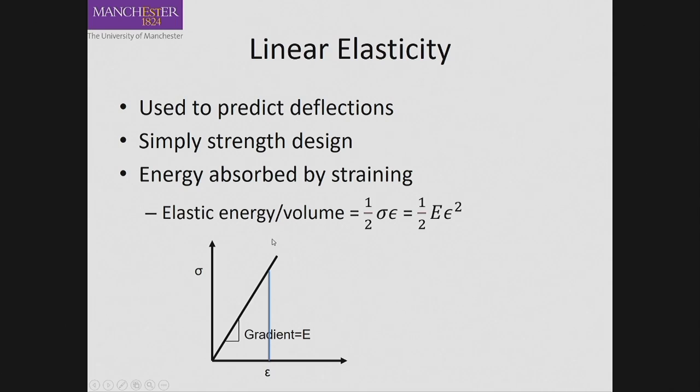So in one of the methods that we'll be learning, if we want to find the deflection, for example, or a displacement, you could find out how much is the work done by the load. So half T times delta. So a delta bit you are interested in. And if you know somehow to calculate this elastic energy, strain energy, then you can equate those two, multiplied by the volume appropriately. Then that will give you the delta. Okay, so there are various methods related to that. We'll look at that.